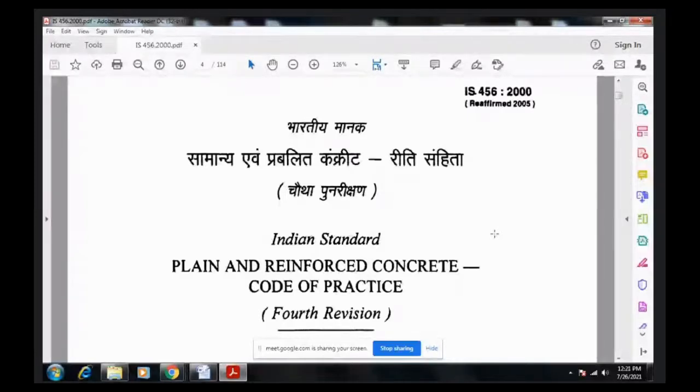And already, based on IS 456 and structural mechanics, we have said width equal to 500, depth equal to 500, and the bottom reinforcements, say 16 millimeter bars, about 3 numbers, 3 16 millimeter bars, longitudinal bars along this span, and say 2 bars along the span.